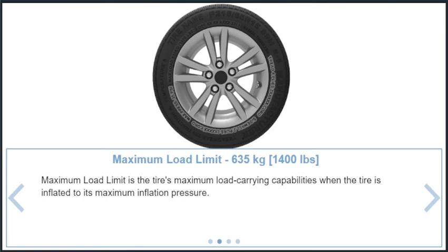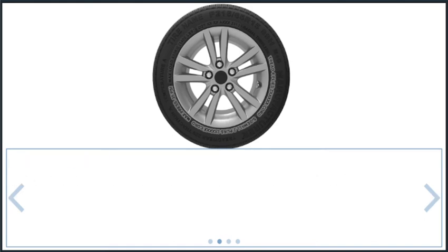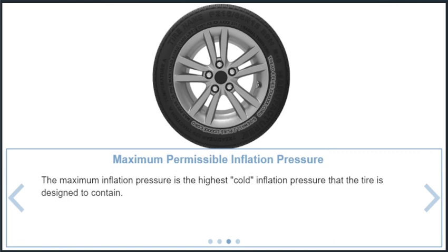Maximum load limit is the tire's maximum load carrying capabilities when the tire is inflated to its maximum inflation pressure. The maximum inflation pressure is the highest cold inflation pressure that the tire is designed to contain.